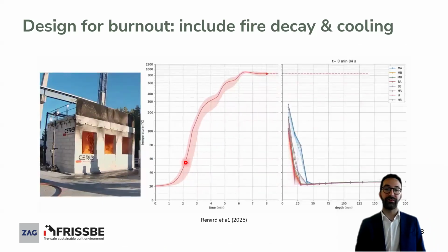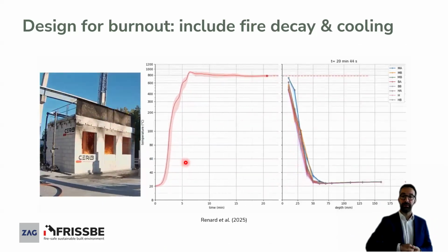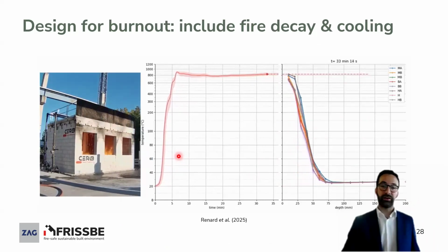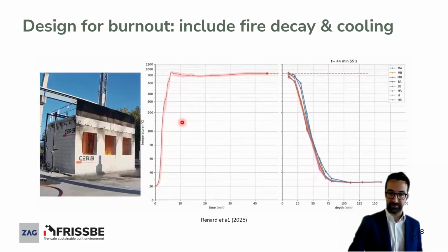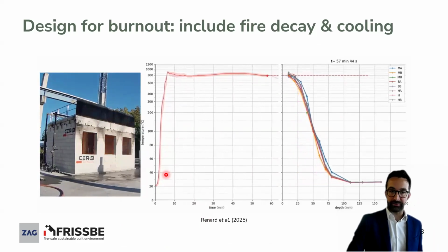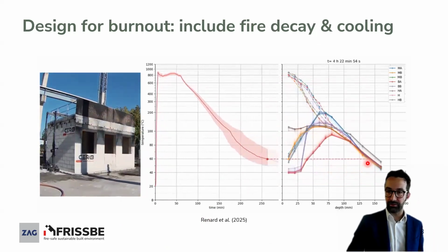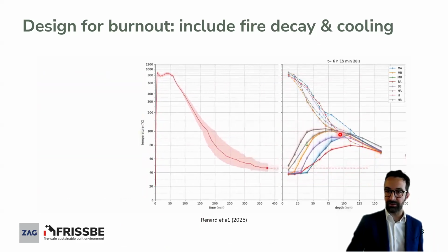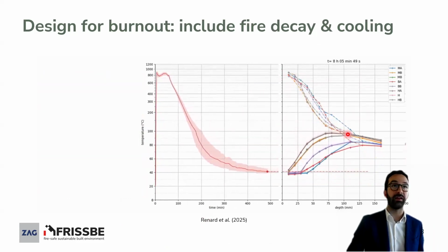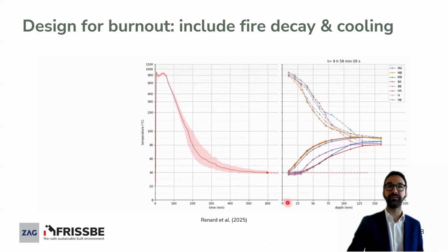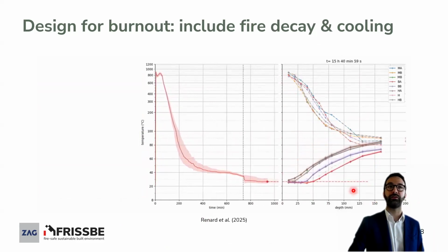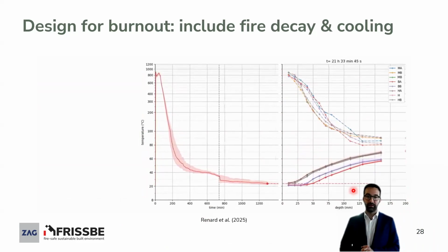And this is also another fire test that they did in France at CERIB. There you see the fully developed phase of the fire, this is like a logarithmic scale, and I found this online, but you see that this is the gradient during the test, and then you see that temperature still penetrates inside the wood. These are the gradients through the wood during the experiment itself.